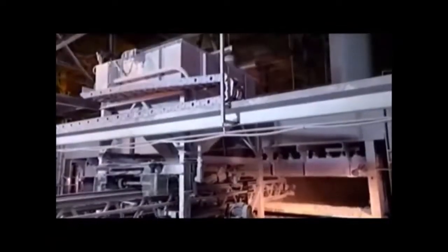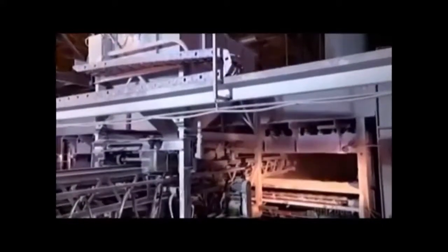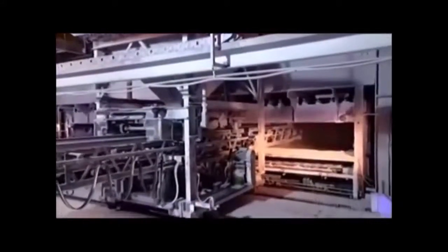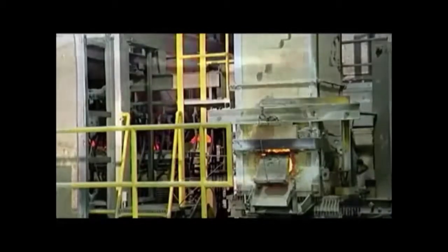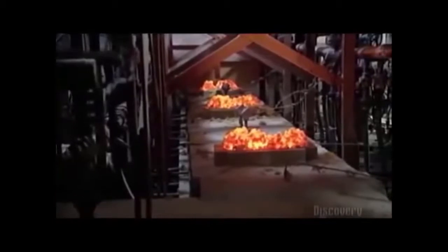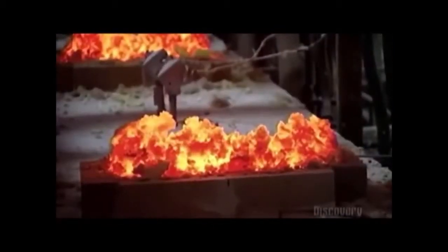The cullet and batch ingredients spill onto a conveyor belt system, which transports it all to an electric furnace. The conveyor moves back and forth to evenly distribute the cullet and batch ingredients. They seep down and melt into a previous mix, which is now a pool of glass at the bottom of the furnace. The glass liquid now flows out of the furnace and into sloped channels. Inside these channels, the temperature is kept red hot by natural gas burners. This keeps the glass mix in a liquid form, as it oozes out of holes in the bottoms of the channels.